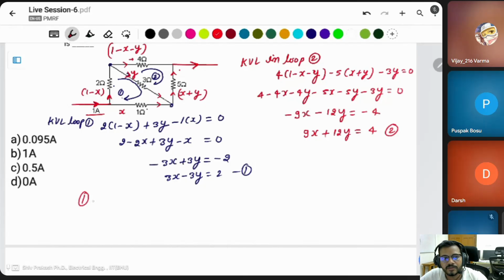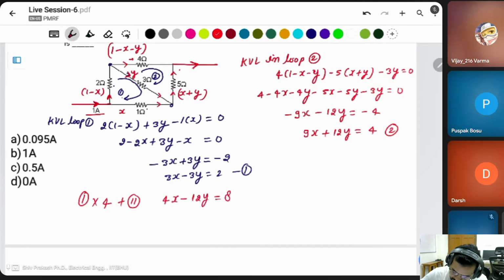Okay, sir, there are 3 ohms in between, that's why you can say that. Yes. If this is shorted, then you can say that this is a current divider and simply apply it. But there is a resistor, so you can't apply the current divider here. Current divider or voltage divider only applies where there is a directly series and directly parallel combination. Yes, sir. Now I understood.